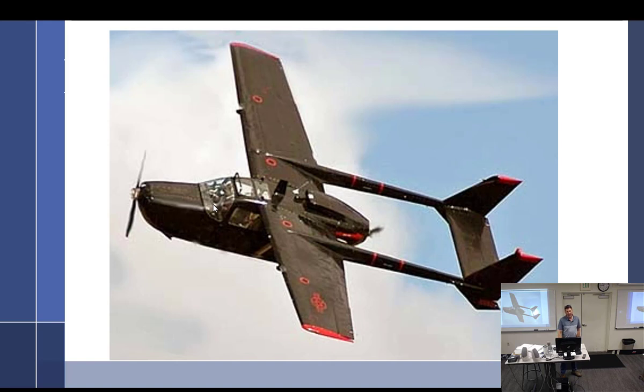And you want to compound that with the type of landing gear that the 337s had. 336s were fixed gear. 337s, Cessna has a really weird gear. If you've never watched it retract, it's just the most bizarre thing. It starts out like this, and then it drops down, and then the wheels twist, and then it goes back up into the belly. Well, when the gear drops, it actually drops down quite a bit first, and twists, it creates a tremendous amount of drag.